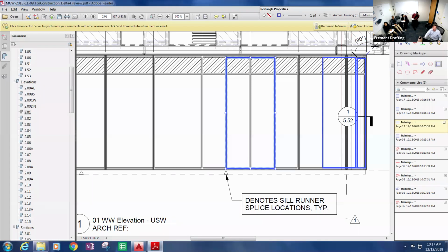And then half of that, there's a setting chair on either side, which is coming down. So for dead load, that's my tributary area. For wind load on that anchor, let's go orange, that's my tributary area.